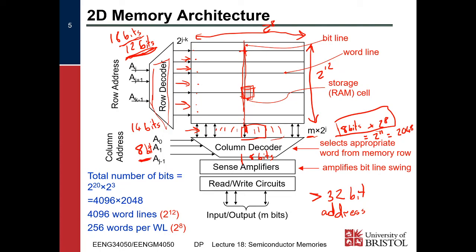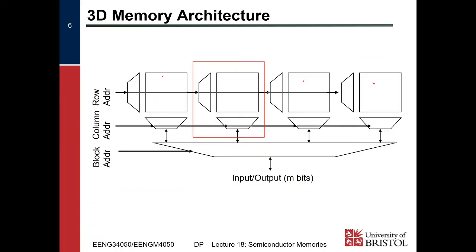So that's decoder 2 there, and this is decoder 1, decoder 1, decoder 2, decoder 1, decoder 2. So if we just say a 1-bit block address, we can have the two different decoders working on every other line, and that reduces the aspect ratio by a factor of 2, right? So that's exactly what block addresses are doing.